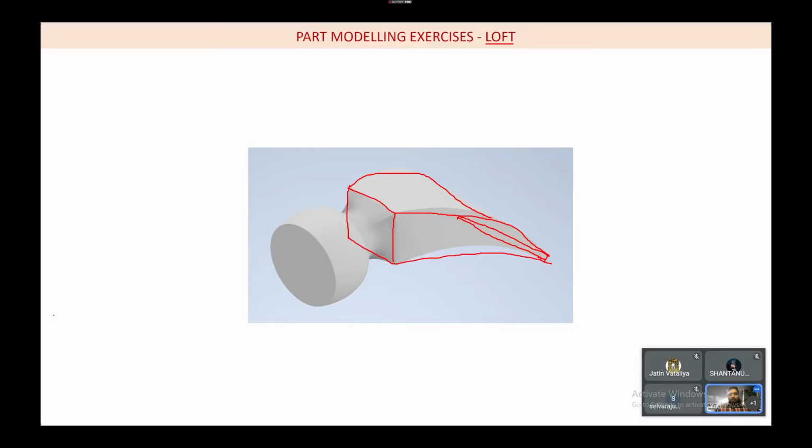Now if you see, this is now at an angle of 90 degrees to this plane and it is passing through this edge. Any doubt in this? First I created an edge in this plane, and now I want to create a plane which is at some angle. Let us say it is around 45 degrees to this, and it is passing through here, correct? So let us say 45.